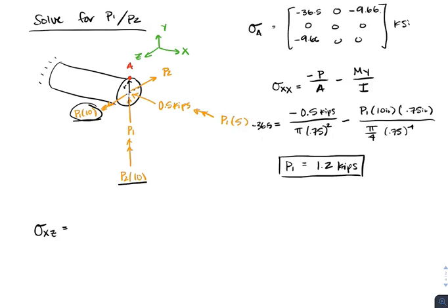So if we look at our shear forces first, we have our P1 and our P2 shear forces. Our P1 force is going in the positive y direction, but since it's in the same direction as where that point is, it's like along the same axis almost, at each end of a shear force that's going in that direction, it's going to be equal to 0. So where point A is, the shear force due to P1 is also equal to 0. So we don't have to consider P1, just like how we didn't have to consider this P2 times 10 moment.